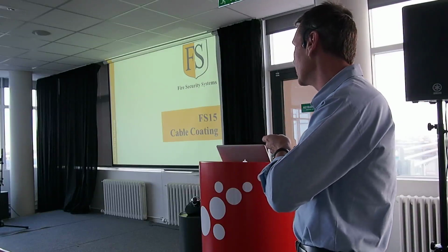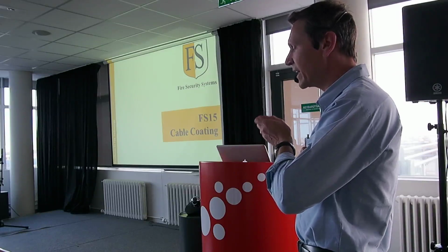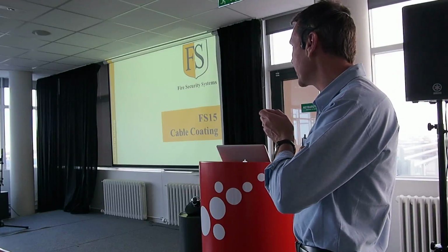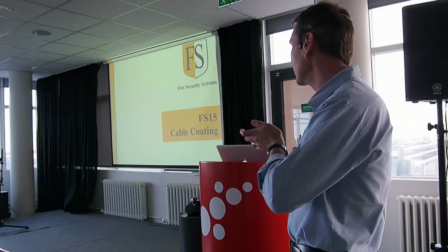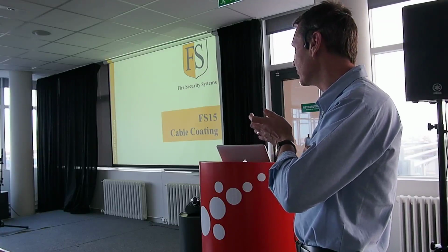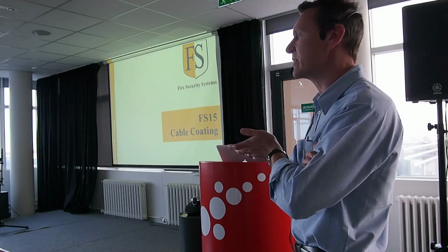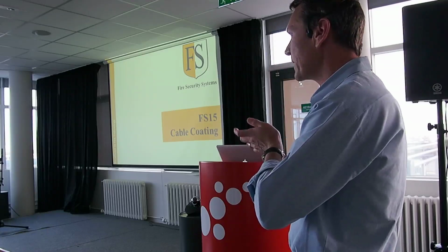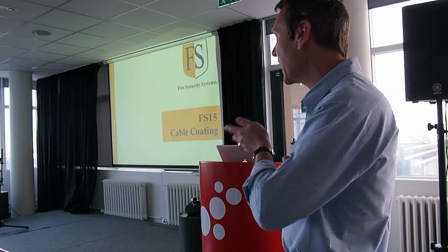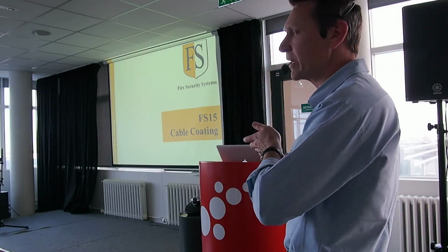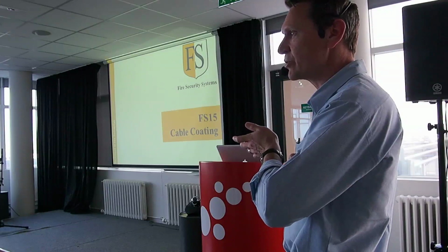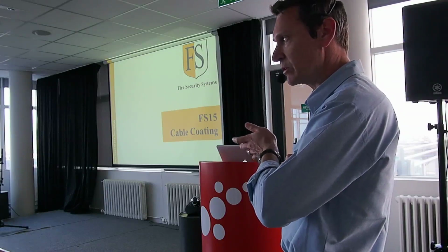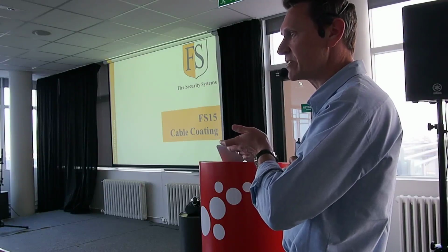HDPE is the same. So with our cable coating, we coat the electrical cables, in the trays or singles or in bundles, to the gland of the machine, which means that if there's a fire, the fire stays at the machine. The MCC or the switchgear or the switchboards, it does not spread through the cable system. And as you saw before, even under direct fire, you replace the cable coating, not the cable. It's a sacrificial coating. It's a permanent solution, but it's still sacrificial. It's there to save the cable.